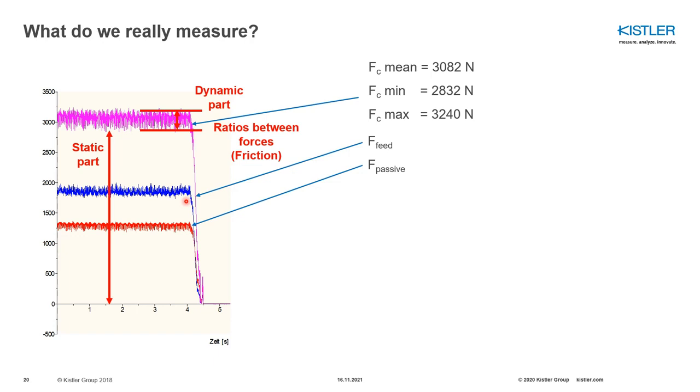So if you are working with understanding and making research on cutting forces, you need to consider and look at those 3 properties of a cutting force measurement. The force signal consists of information about the chip, how chip formation occurs, tool wear and tool wear type, and surface quality, which depends on dimension and roughness.